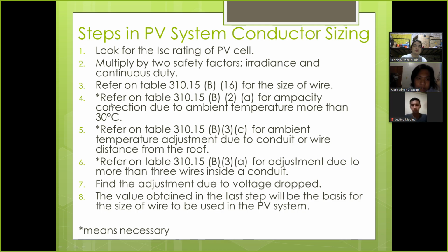Number 4, i-refer naman sa 310.15(B)(2)(a) for the ampacity correction, kasi nga hindi 30 degrees Celsius yung ambient temperature sa Philippines. So, may adjustment. Number 5, refer on table 310.15(B)(3)(c) for ambient temperature adjustment due to conduit or wire distance from the earth. Yun yung sinabi ko kanina na kung gaano kalayo yung wire dun sa bubungan.